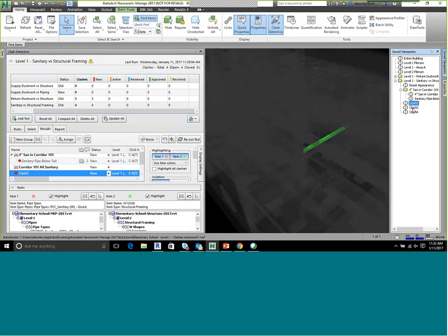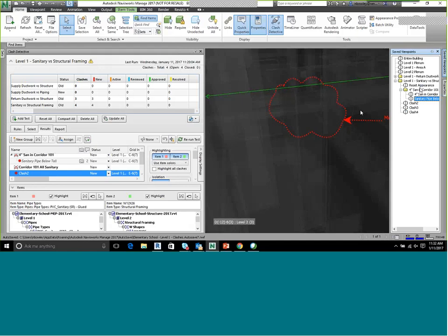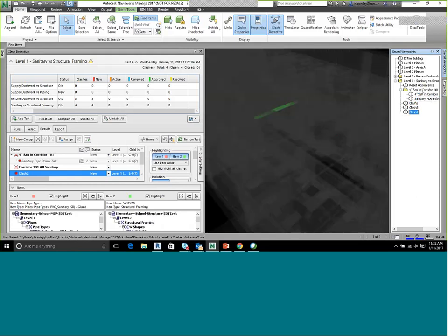So don't do your comments in these save viewpoints, not for clash reports at least, because these are really an export. They're really one way, and they're for the benefit of somebody who maybe doesn't have Navisworks Manage, and they're just going to be viewing the clash report or the clash comments that you want to send them. Anybody with Navisworks Simulate or Manage can navigate these views. I had a slide for it, but I don't want to go back to the PowerPoint.